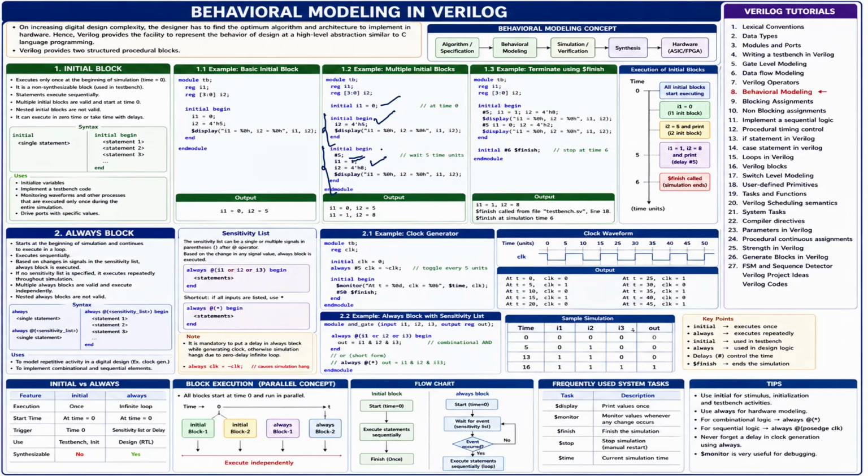At that time, we will use another initial begin block. Here I'm executing one data, and here also giving another input. So for two inputs I will give a single initial begin block. With these two initial begin blocks, I don't know which initial begin block is taken first. That is the reason we are avoiding multiple initial begin blocks.